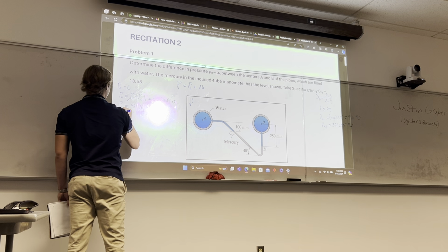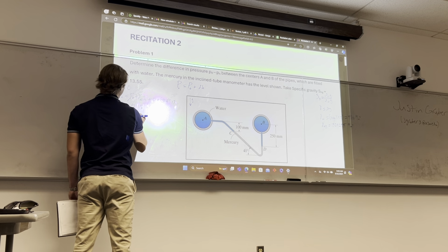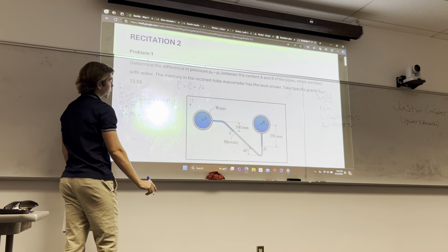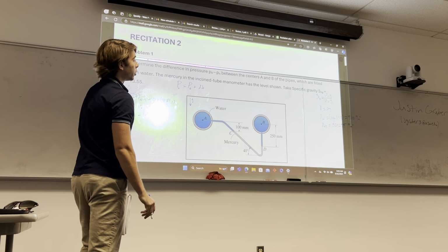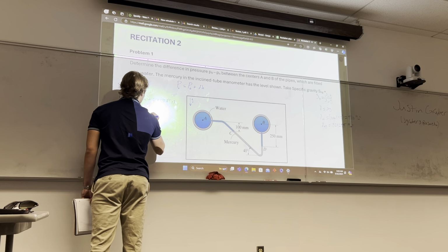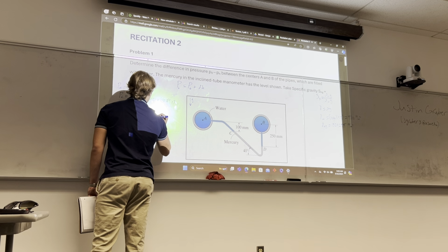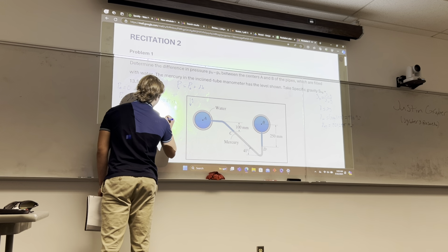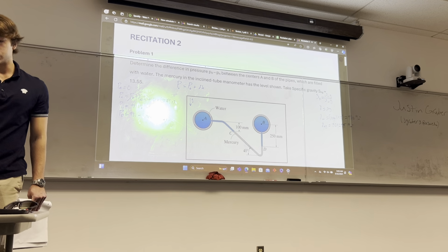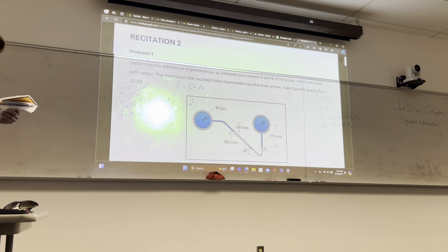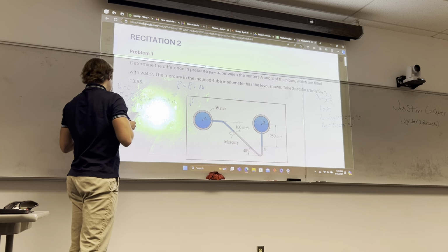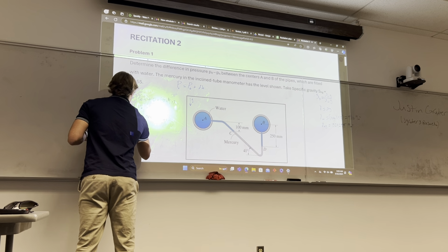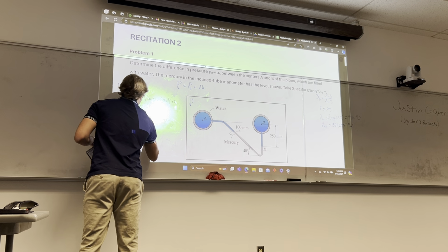So point D equals point C, which is 981, plus gamma of mercury now. That really big number, 132,925, times the vertical height of the column, 0.15 meters. This is a significantly larger number, which is 20,919.825 pascals.